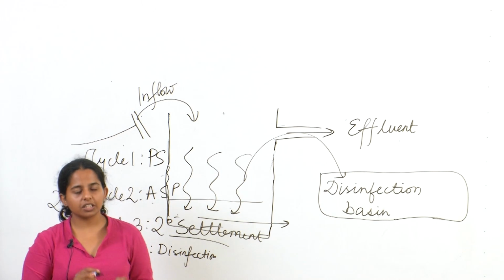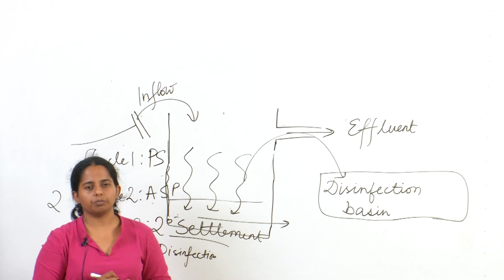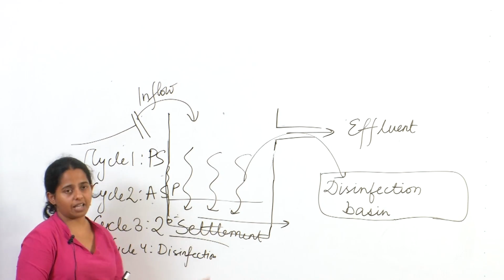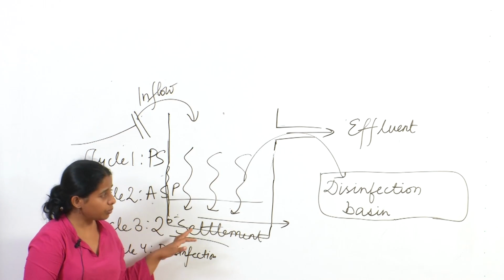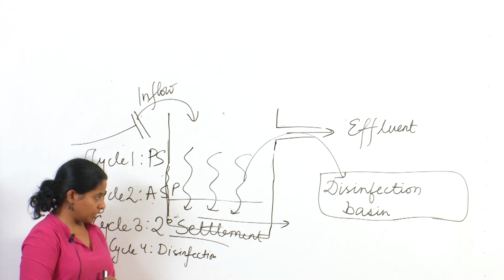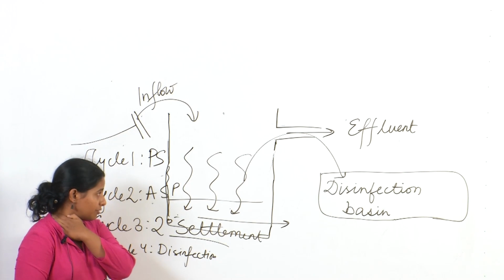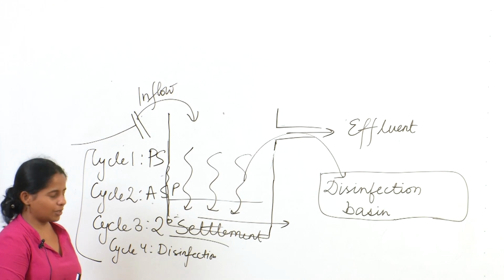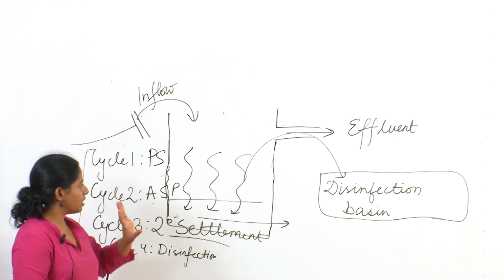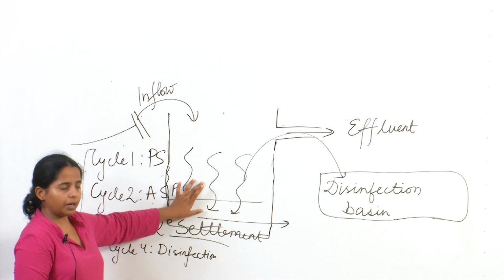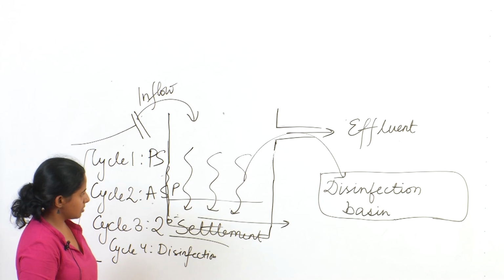So the key difference between SBR and the PFR based ASP process is that in SBR all the processes happen in a singular tank. This is very important for a country like India where land is a precious resource, because we are running out of the land that is available for setting up expansive ASP processes, but our population continues to grow. It is very, very important for us to consider such less land occupying SBR based water treatment systems.